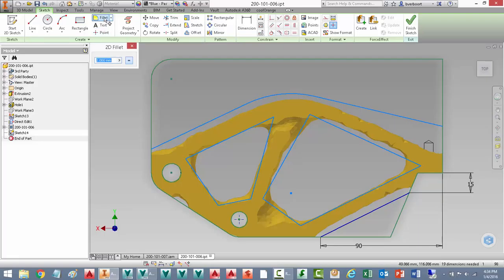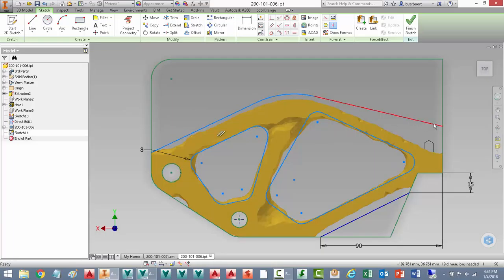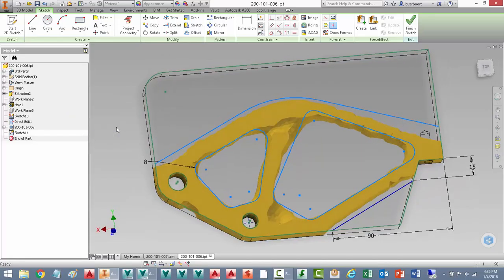Since we know this is going to be a conventionally machined part, we'll add in some fillets here at the sketch level, which will help us describe the geometry a little bit better with a little less trouble. And just a couple nudges here to get things more located with the size and shape we're looking for. I'll right click and we'll finish that 2D sketch now.